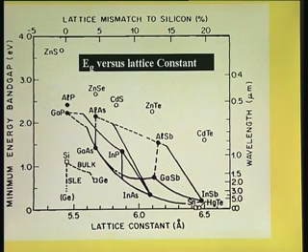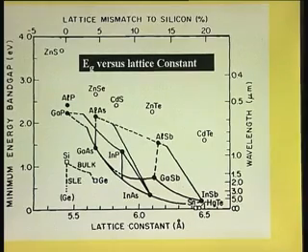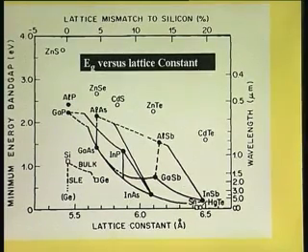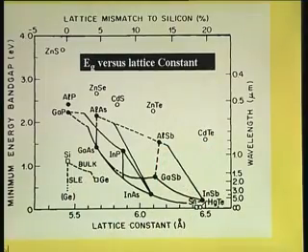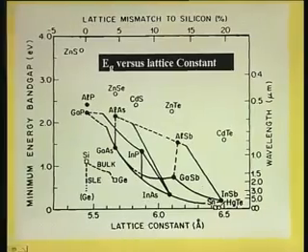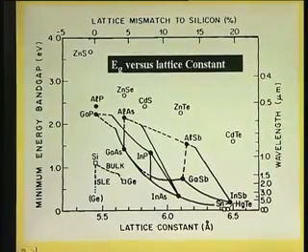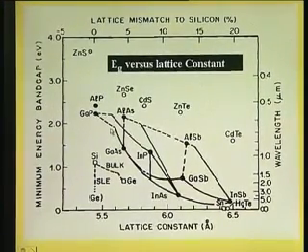From the top, all these compounds are the 2-6 compounds, which we have virtually eliminated from the microelectronics agenda, because their mobilities are low. Their band gaps are excellent, much higher than that of silicon in all cases, but we do not want it for microelectronics, but they are useful for optoelectronics or photonic devices. Now, let us see the ternary compounds.